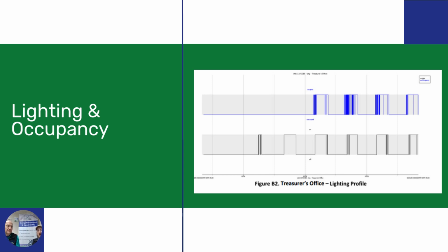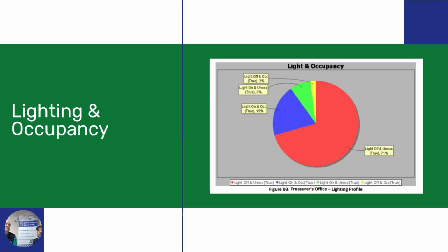Most buildings, even ones that are really considered 24/7 or continuously operating buildings, do have some areas where there's transient occupancy, like conference rooms or restrooms or maybe some different hallways. And so we want to not just broadly make that recommendation that, hey, you should put lighting controls in. It's probably a good idea, but the data will help us not just determine is that a good idea, but it'll help us quantify it.